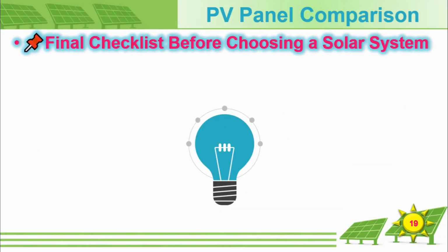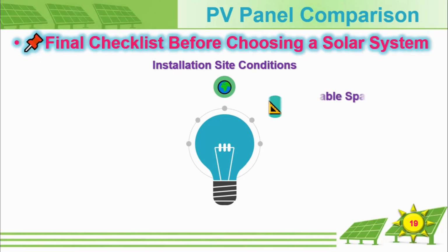To determine which panel you should choose, you can consider the following factors. The conditions of the installation site. Consider the amount of sunlight. These flexible panels suit special conditions. Use this checklist to decide. Consider your site's sunlight hours, average temperatures, and factors like dust or humidity levels. How high is the probability that there will be shading caused by nearby tall buildings, leafy trees, or even atmospheric pollution in your area? Furthermore, the availability of physical space can often become a significant issue.